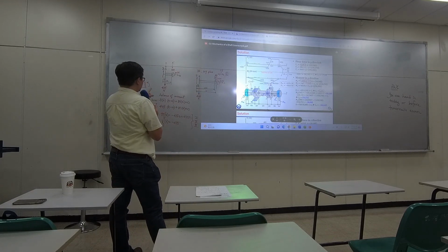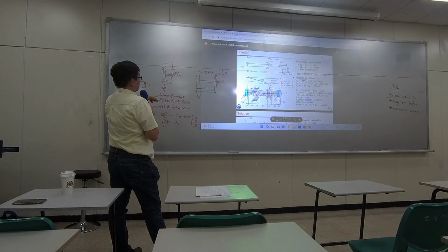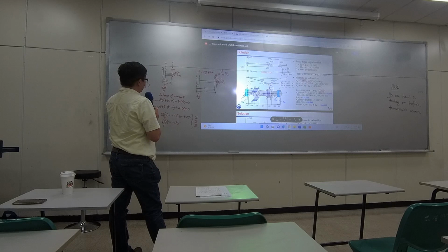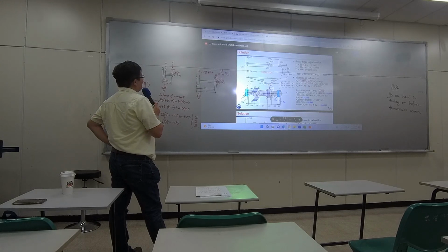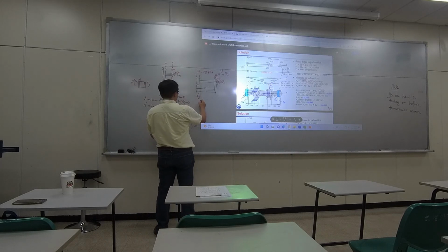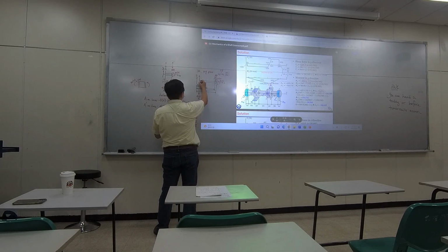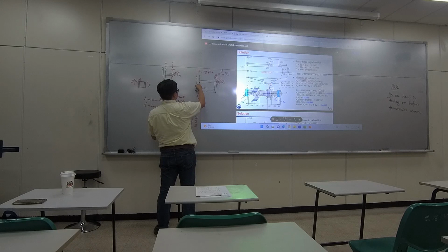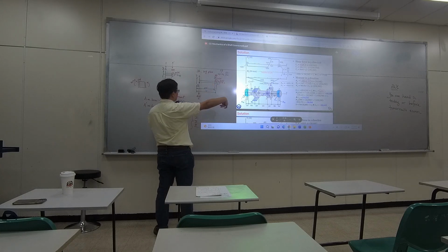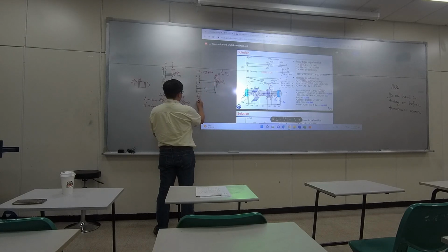Now, what you can do is to do balance of moment as well, but you need to choose some points as your base point. You can again use A as your base point. So if I choose here as my base, then Vx is making a clockwise moment, so I'm gonna do that.